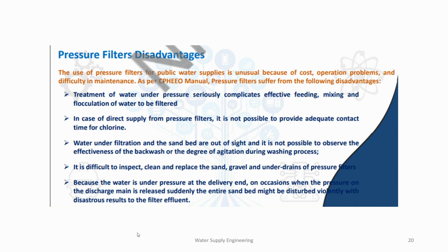Yes, yes. Okay, so in this case, the water is continuously under pressure, and once the fed water is treated, it will be automatically pushed out to the discharge main or the delivery point or the outlet pipe. So it won't be possible to maintain detention time for the water or retain the treated water, so that the added chlorine gets sufficient contact time.